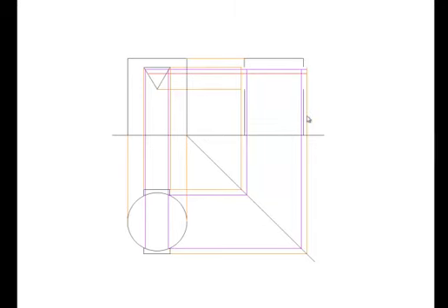Again, like before, the red line will intersect the prism in points here and here, and like before, we will drop these points from elevation to plan to locate 4 more intersecting points. These points are then rotated from plan to the end view and create another 4 piercing points, like so, 2 at each side.